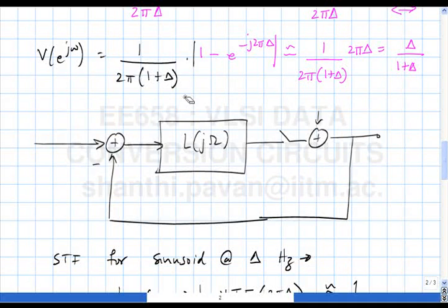Okay, and please notice that in an anti-alias filter what you need is in principle notches in all the alias bands, correct? You don't really care too much about what happens elsewhere as long as the alias bands are all notched out, and that's exactly what this is doing for you, because in the alias bands the NTF is 0, correct?